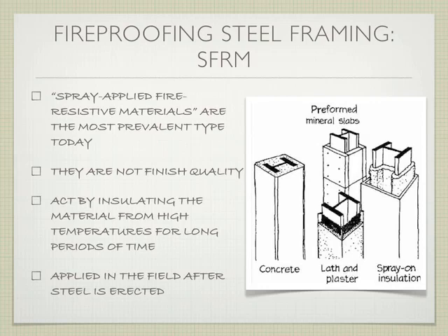We can also put on what are called spray-applied fire-resistant materials. I'm not putting the hour ratings on the slide, so I'll look that up and make sure we get that information to you. The spray-applied fire-resistant materials are the most prevalent type today. They are not of finished quality, so they're not something you're going to want to look at.